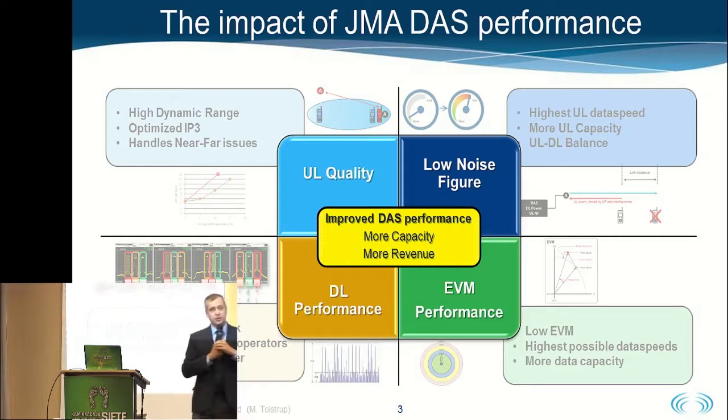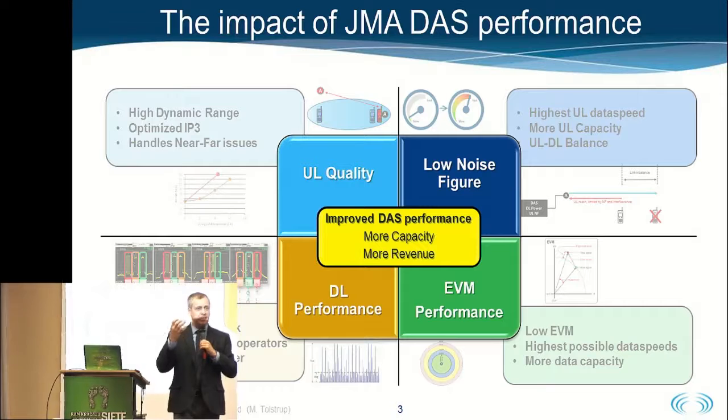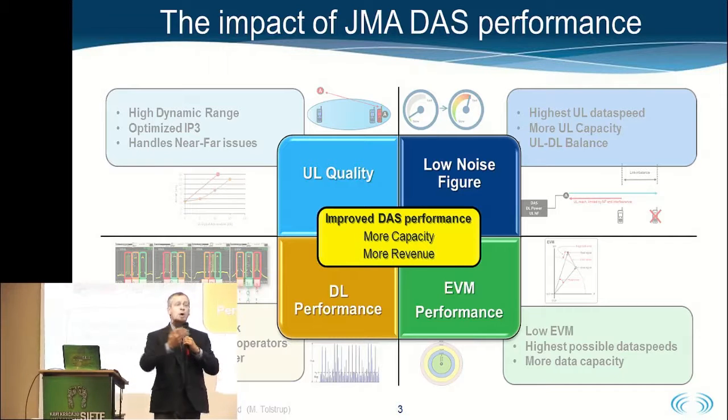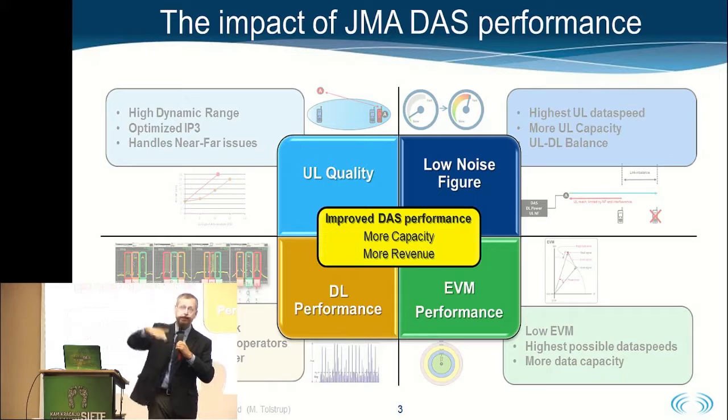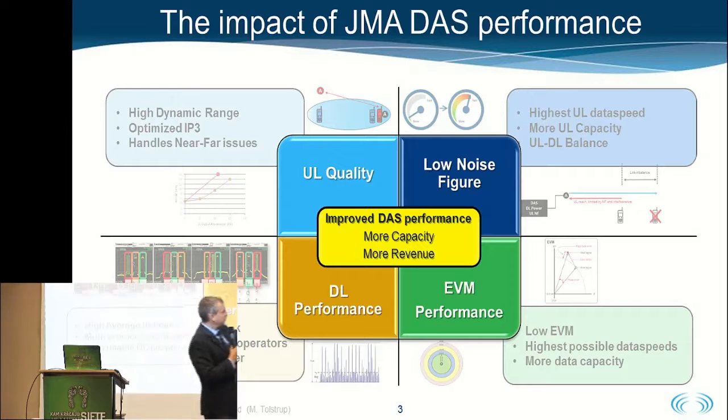One parameter is noise figure. Without being too technical, I would say this is the same as loss in the system. So the more coax you have, the more attenuators, the more loss you have in the system, the less capacity you have. So that would be the limitation for the passive solutions. Then we have some critical...